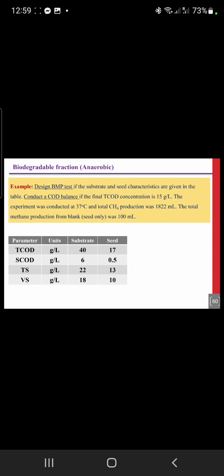And the seed, so most of the time, almost all of the time, in environmental engineering we represent substrate as COD and seed, your microbes, as VS. So your microbes we present as unit of VS, grams of VS per liter, or grams of VSS, like I talked about, suspended solids, per liter of the environmental matrix. It's mainly water that we're talking about though.